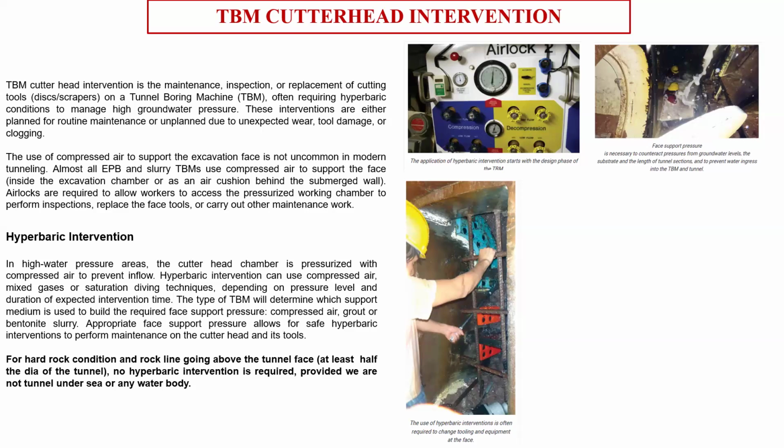So basically they don't have any extra excavation at the side. It depends. Sometimes in a very tight curve we use copy cutters, but a copy cutter is a very specialized system. As I told you, the TBM features that come with it depend on many factors, and there are lots of things that do not come built in, so you have to install additional features if you think they are needed.